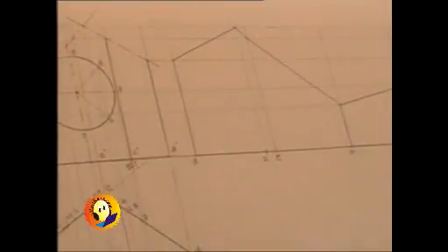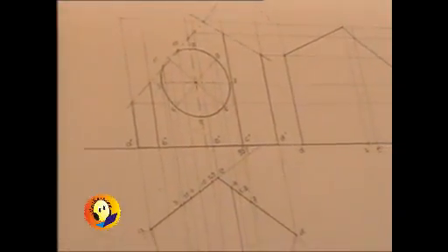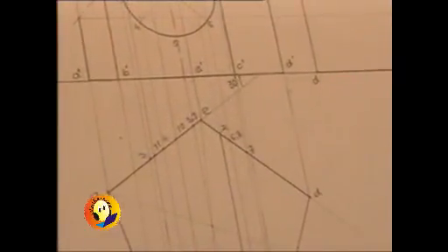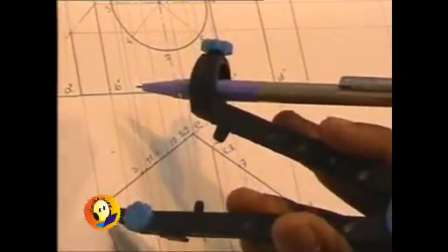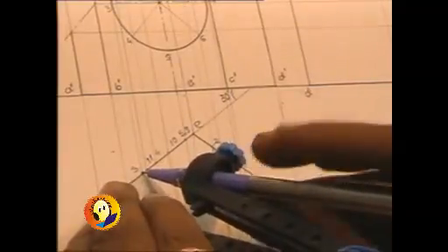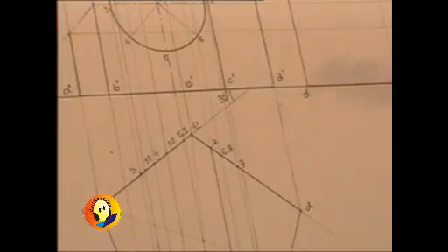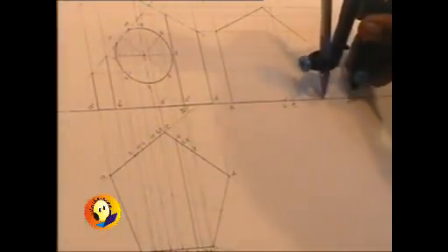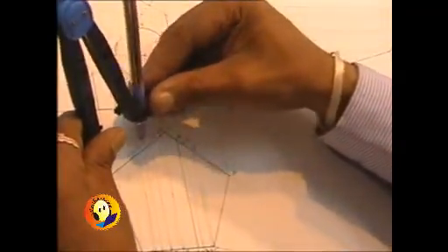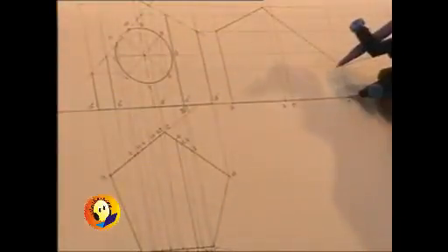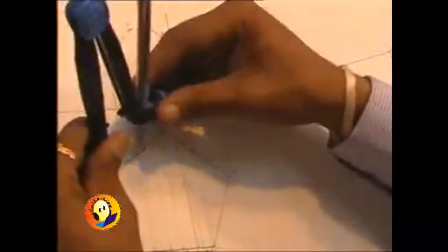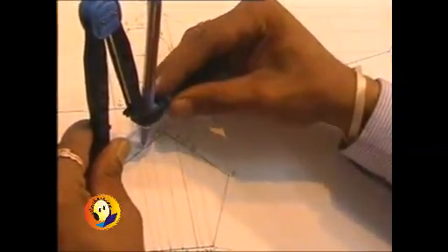Similar generators we also have on the two sides, namely AE and DE. So we are required to now take the distances, say from A towards E. Distance A3 is to be taken, and it should be marked on the development from A towards E. It is 3. Then from A up to 11, take the distance, and from A towards E mark it. Then A4, take the distance A4 and mark it.